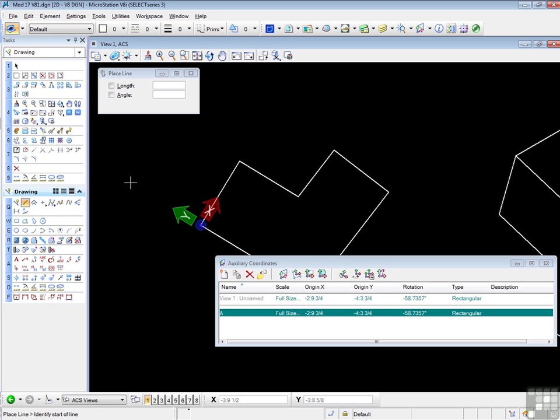I'm going to right-click to stop that, snap to this point, F11 and O key, put the compass there, move outwards a little bit, start the first edge of the auxiliary view, and I think I should change that to a weight of 1. Hit enter to lock myself to the axis, find this corner, go in this direction. Again, no dimensions, so any dimension will do. Drag this way, enter, find my corner, come back to my corner, and there's the start of the auxiliary view. So obviously a very simple thing to do with the rotated compass. And I'm going to leave that there for the moment.